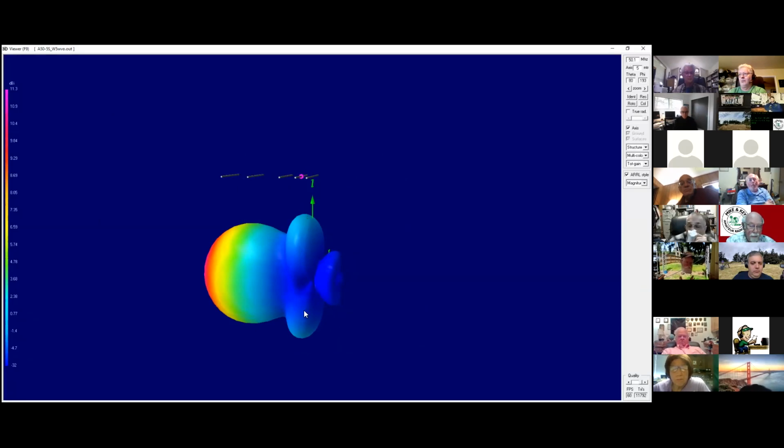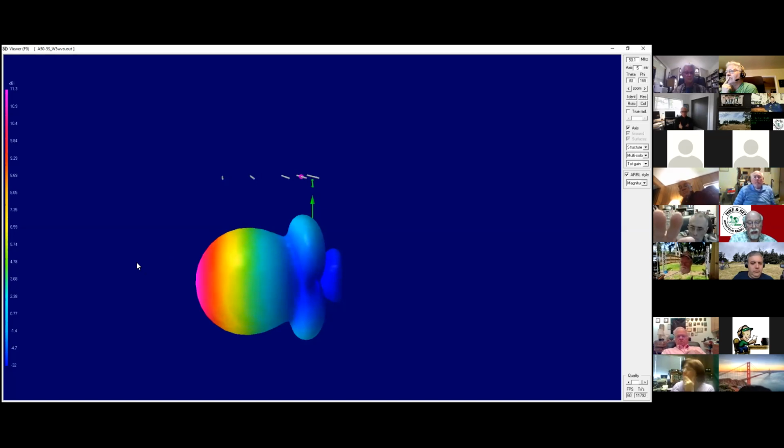Well, you pick up local noise sources like there's no tomorrow. And if you look at this, this is approximately 3 dB that you're amplifying your local noise source. For 6 meters, this is pretty bad because you do a lot of weak signal work on 6 meters. So if you have any local noise sources at all that get amplified, your ability to copy a weak signal that's in the direction your beam is pointing is pretty poor.